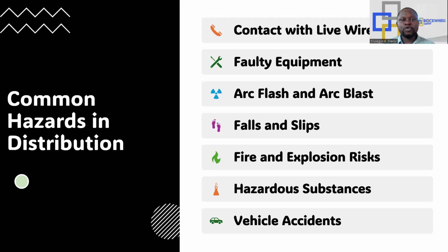Let's assume you are going to carry out a task on a line, and you de-energize the line, and someone is actually working on that same line, and the person did lock out, tag out. And you are also going to do another task on that line, and you get to that place because you want to do lock out, tag out, and you discover that somebody has done that. What are you going to do?